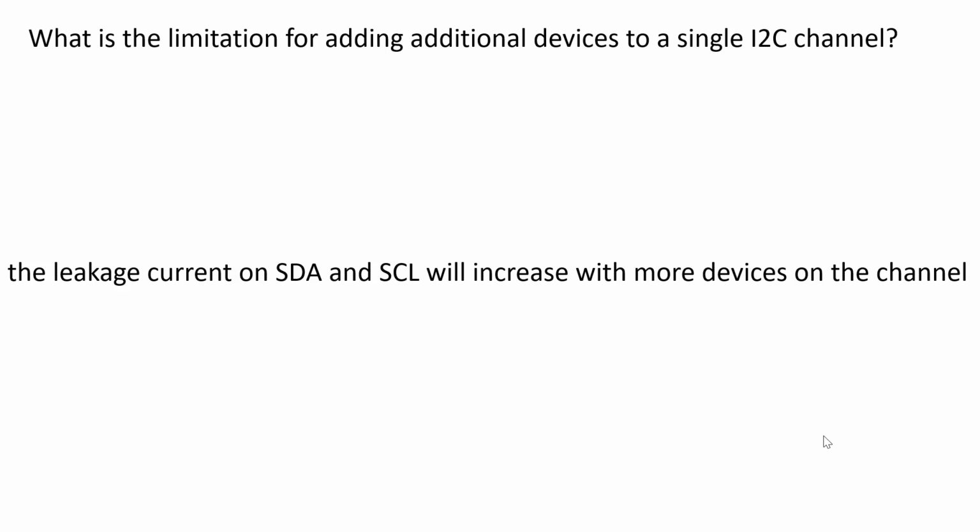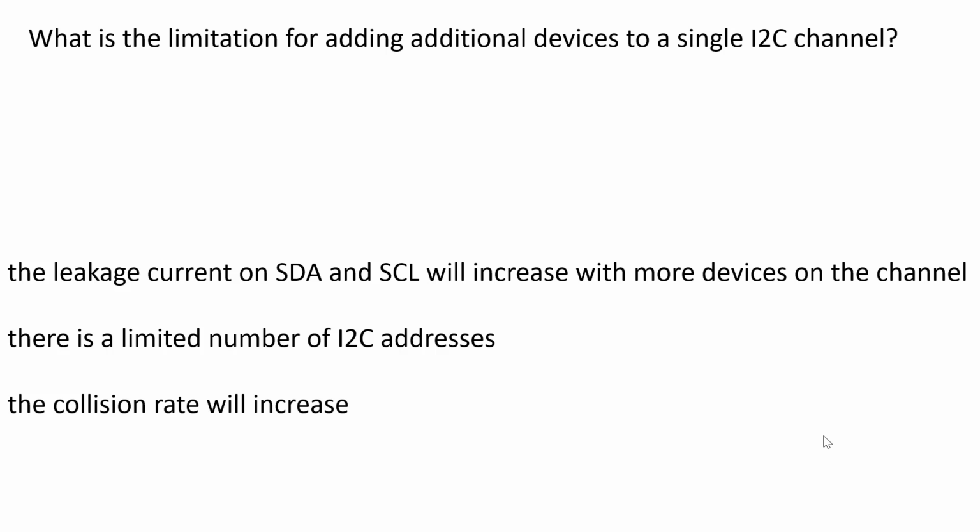I think the more devices you add, the more parallel resistors you'll have. Oh, and there's a limited number of I2C addresses. Oh, yeah. And the collision rate will increase because you'll have more contention on the bus.